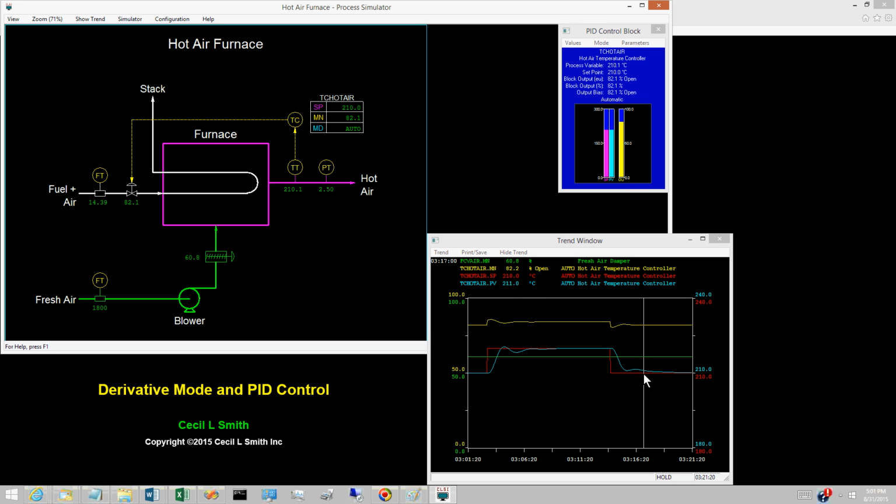Although sometimes used, let's avoid the expression more stable. A loop is either stable or it's not. A loop whose oscillations grow rather than decay is unstable. A loop whose oscillations decay is stable. Both of these responses are stable.